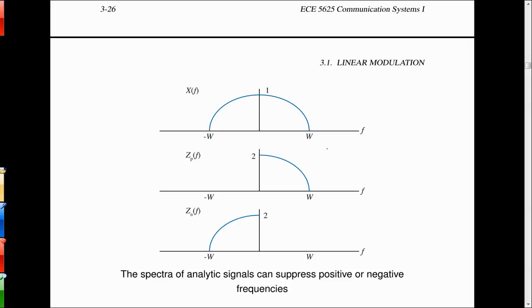Will they age the same? They won't be. But if you can get it done with a single A to D, then you can form what's called the in-phase and quadrature signals from a single converter. And one approach is to do it with the Hilbert transforming filter. Then there's another approach called IF sampling, which is probably a little bit more popular these days, but it just depends on how the front end is to work.